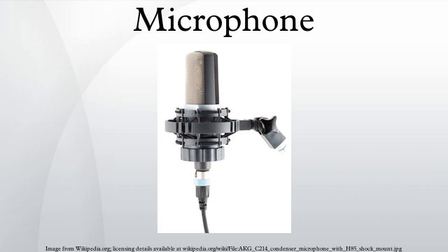In more mathematical terms, while omnidirectional microphones are scalar transducers responding to pressure from any direction, bidirectional microphones are vector transducers responding to the gradient along an axis normal to the plane of the diaphragm. This also has the effect of inverting the output polarity for sounds arriving from the backside.